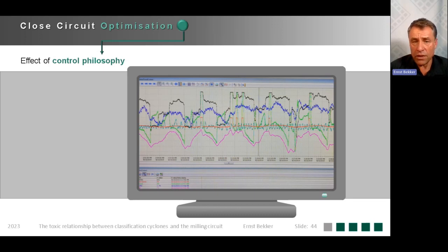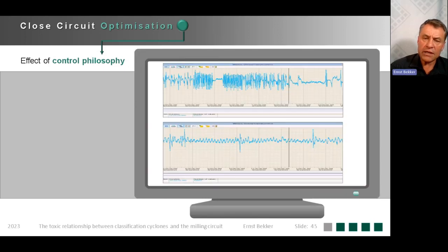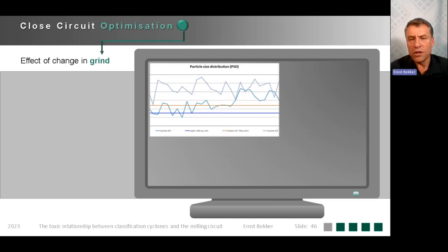So the question was, or the clients requested, to look at alternative cyclone configurations or alternative cyclones to get out of this coarse misplacement. So the focus was on the efficiency of the cyclone. But when asked about the mill discharge sump level fluctuations, it turned out there's a flotation process up front, and that oscillating level is coming from the flotation. The suggestion was made to run the pump in a manual mode to take care of the fluctuations, and that is the type of pressure fluctuations that was experienced in the bottom graph on the cyclones after the modification was made.